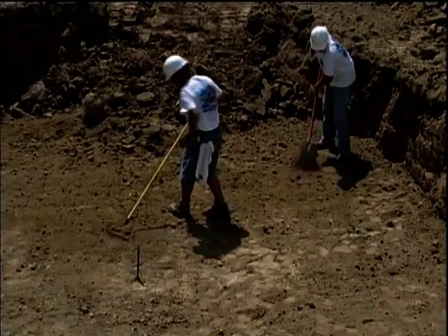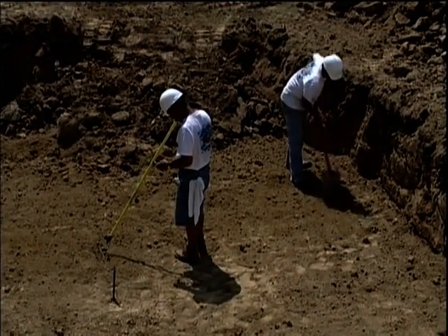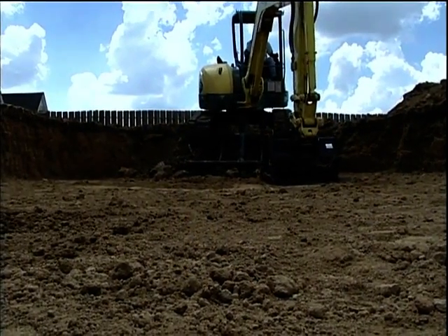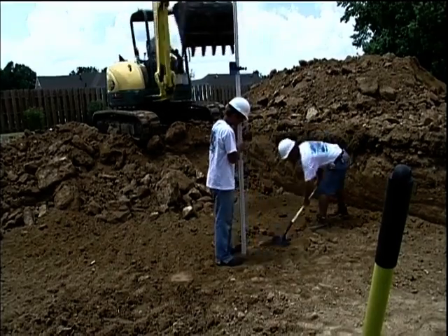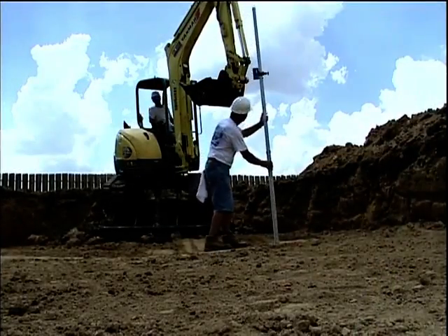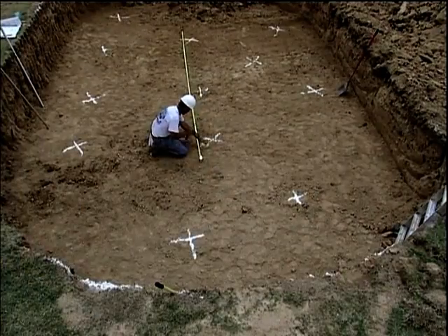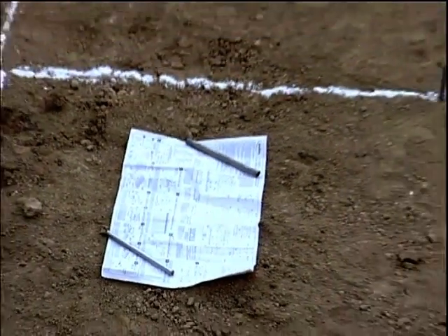When fine-tuning the excavated area, the square shovels will be used until the area is ready for the pool installation. When the excavation is about 2 inches of the desired depth, check the general outline and start scraping down to the desired level, constantly checking spots with the transit, marking the areas that are at the desired level. Once the bottom is level, it is time to refer to the assembly guide section, Pool Layout Dimensions.